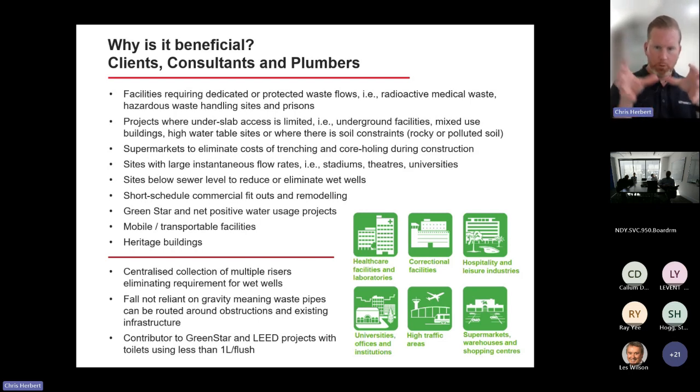So instead of having individual toilet blocks around the actual site that need to be individually emptied, you can daisy chain all those together into a single pipe and take it out to a single vacuum plant, which then can discharge out to a bladder that's off-site. And so you don't need to bring your tanker truck into the festival and have the smell and everything going on while you're trying to empty those individual tanks.